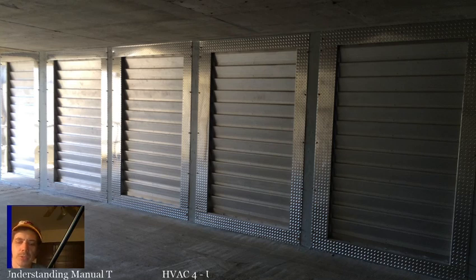And the normal temperature in a furnace is usually going to be about 130. So you will want the fire damper fusible link to be at least 180, and that'll make it a little less likely that you'll get the nuisance trip from a fire damper than if you get one that's set for 160 or something. But anyway, if you see a fire damper closed off of a furnace, don't assume that's what's causing the furnace to cycle off a limit, because there's probably something else that was causing a problem before that.